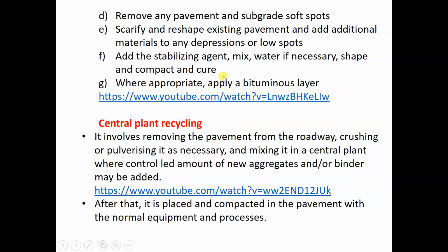Cement: in front they have a cement truck, they deposit the cement, and then they have bitumen as well, a bitumen truck in front. So they mix the two. For this in situ stabilization, they use two additives, cement as well as bitumen, for the stabilization.